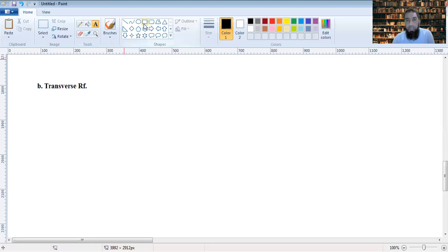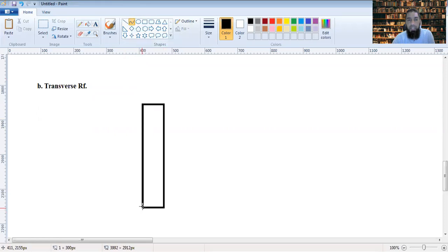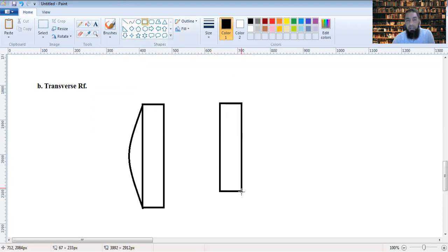There could be a global buckling, which could happen somewhat like this. By global buckling I mean a buckling which is happening throughout the column, some amount of buckling happening like this. Local buckling would mean there is a portion which is buckling out. And that usually happens when the longitudinal bar begins to yield at some point.